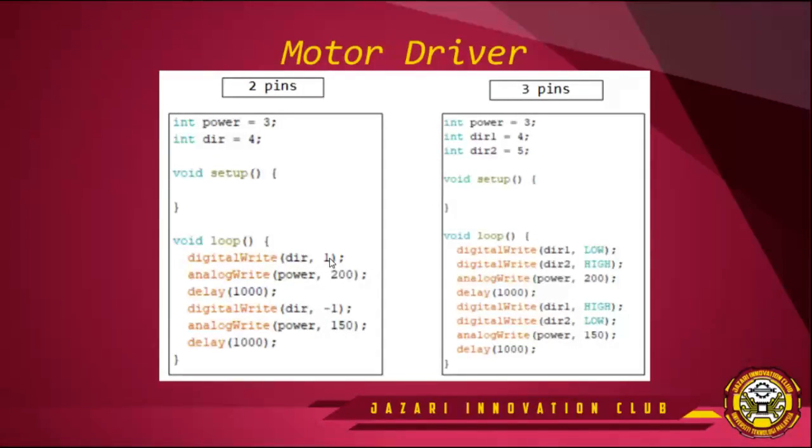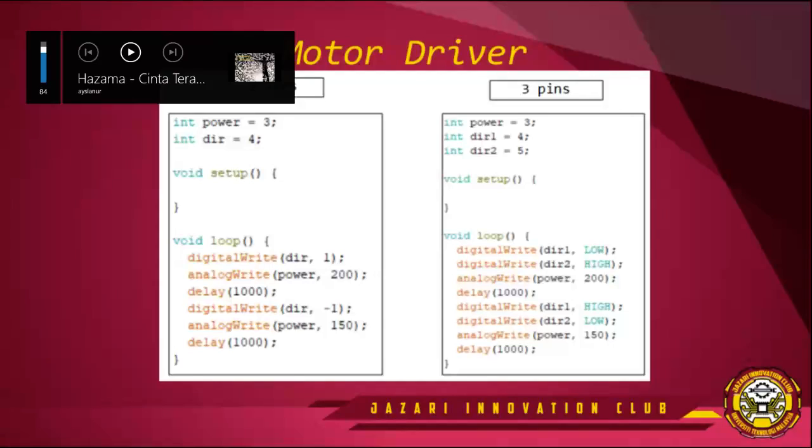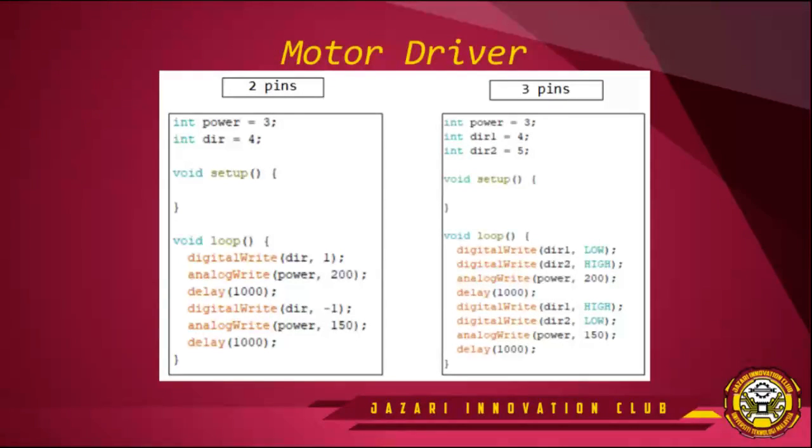If the direction is not as you expected, then you need to change. Let's say you assume if you put the direction 1, your robot will go forward. Instead, it's not. You put 1, the robot goes backward. That means if you want your robot to move forward, you need to put -1. So you need to test by trial and error, to see how your robot's connection is. If 1 is forward, it's okay, but if not, you need to change to -1.